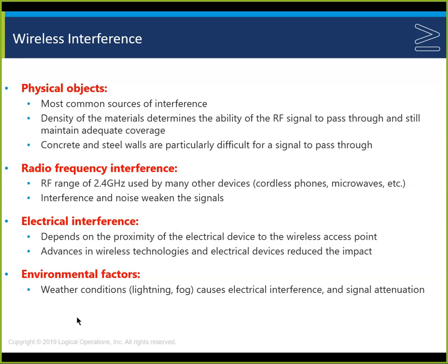And when you think about these things, and this is the not real deep thought questions, you're certainly not going to want to use this in a power station. You're not going to use wired in a power station either, because of the electrical interference that is going to go on. That's one of the places that we're going to need to put fiber in, because we're not going to have the RFI or the EMI, the electromagnetic interference or the radio frequency interference, which we're going to have on copper because it'll induce a signal. We're going to have it in wireless, obviously, because it's going to affect.